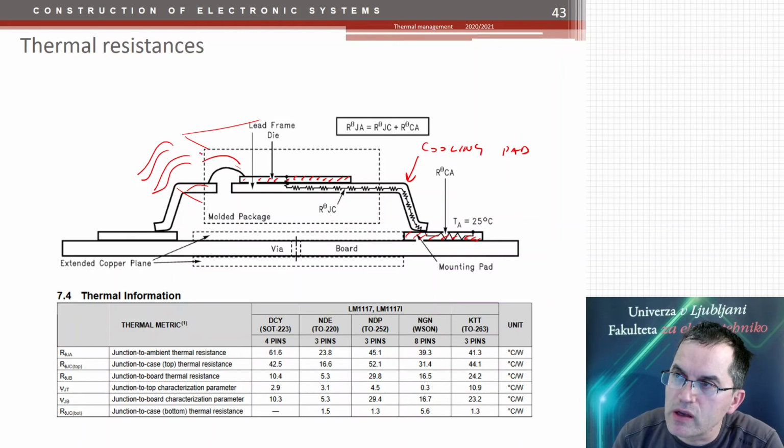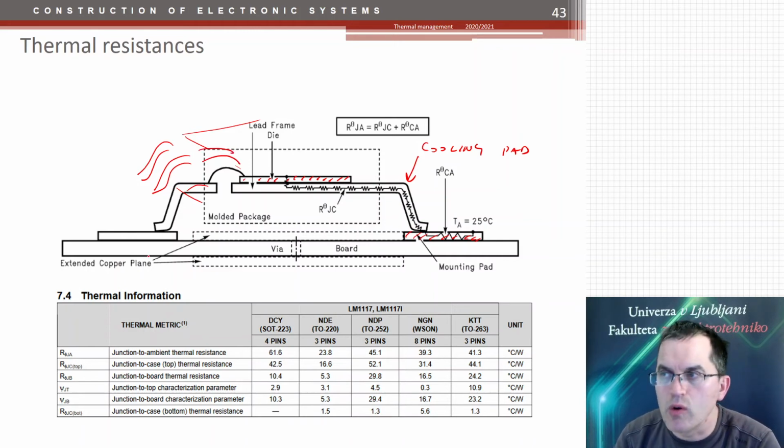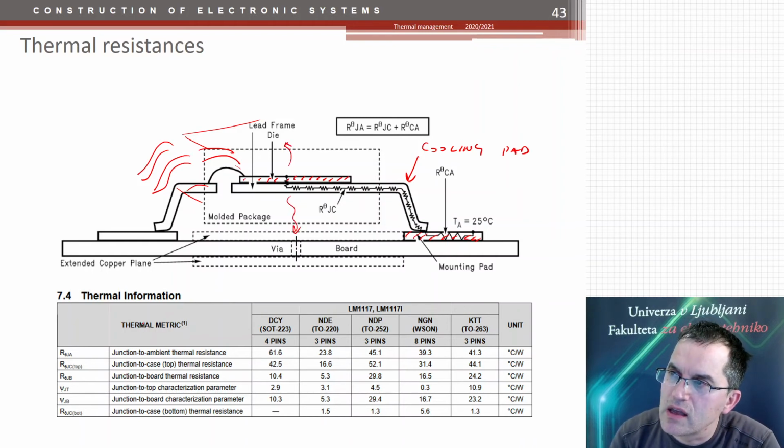And these bonding wires, of course, have very low heat conductivity, which means that they do not cool the component well. And around here you have some plastic, and this plastic is quite a good heat insulator as well. So the cooling towards this and this side is not very efficient. That one is. So you should take care of that primarily.